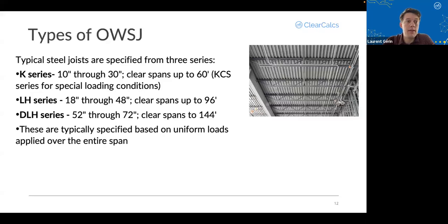When you're looking at these, basically K, you're thinking up to about 60-foot spans. In DLH, for instance, these are like the really big ones. We're talking about 6-foot deep trusses going all the way up to almost 150-foot spans. So these are really long.